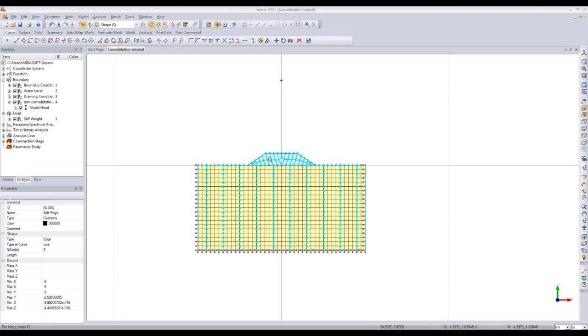Not really. Should it be for the whole soil net, not just the perimeters, right? Yeah, or you choose only the perimeter points. Okay. So this soil here is what's saturated, not necessarily the embankment. That's why I chose the perimeter and not the entire model, and why I didn't include the embankment. But the soil in the box itself is also saturated, not just the perimeter points, right? It should be applied for the whole clay layer.